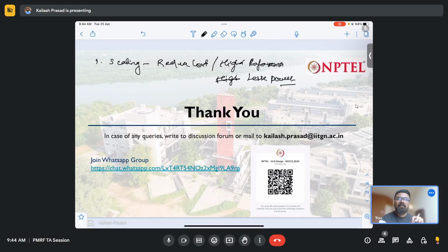Now coming to the challenges, you are actually now printing in nanometers, right? Very narrow dimensions. Even if it is a 5 nanometer technology node, the dimension is 10 nanometer to 20 nanometer. Just imagine how difficult it is to fabricate 10 nanometer, right? You cannot visualize 10 nanometer, but you are actually building more than a city in the area of a 1 millimeter chip, right? Design challenge comes because you are not able to perfectly print it, right?